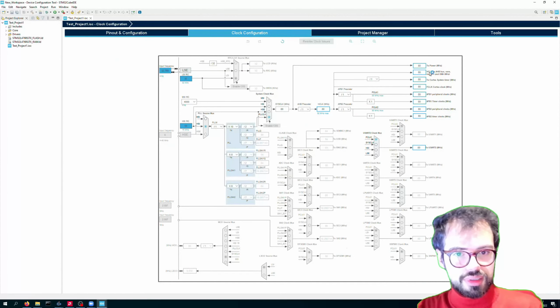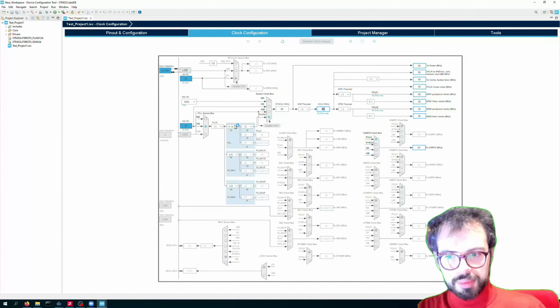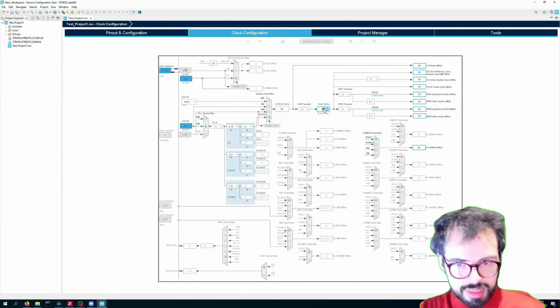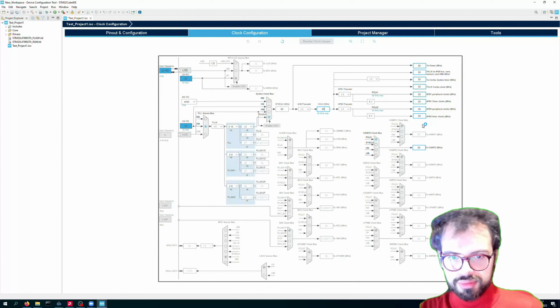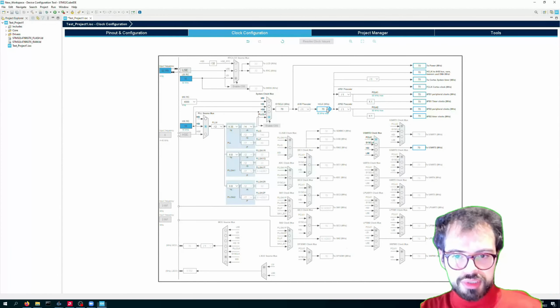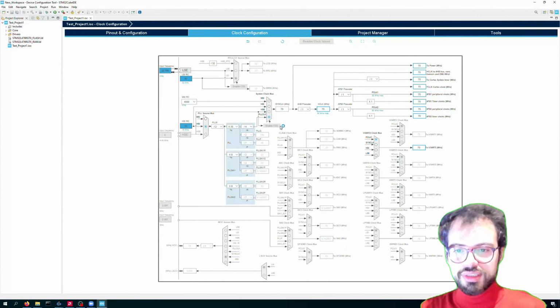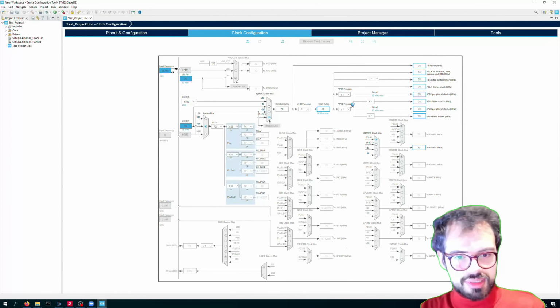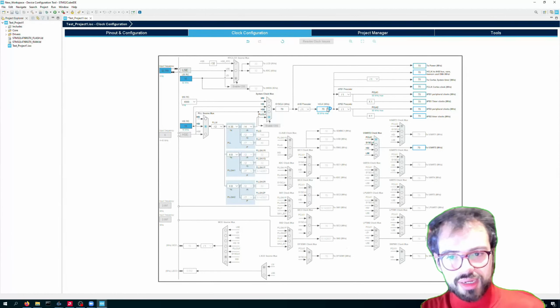You can see that here 80 megahertz is possible. If I want to change it to another value, I can adjust all the parameters here manually, or if I feel lucky, I can take the frequency value that I want to change, and I can just write the frequency I want. For instance, I can put 70, and it will try its best to reach a close enough value. You can see that it did actually. There is a configuration which I have 70 megahertz, which is cool.